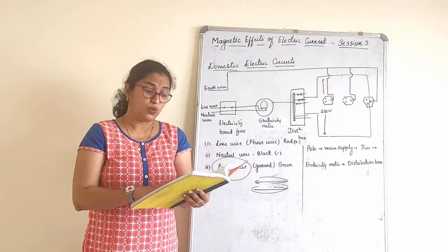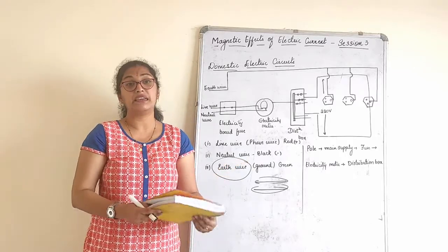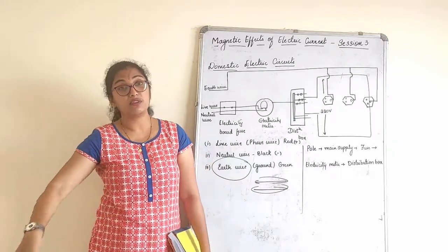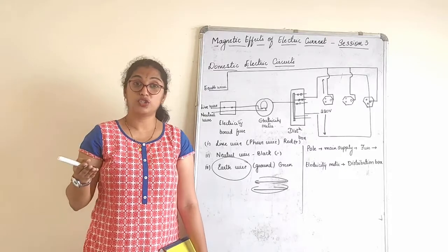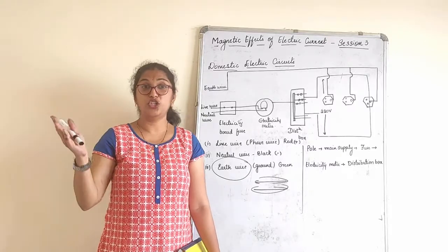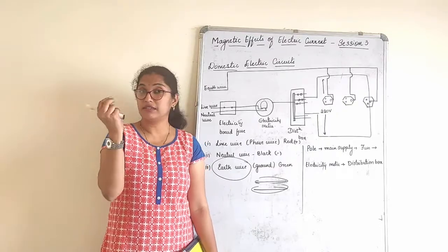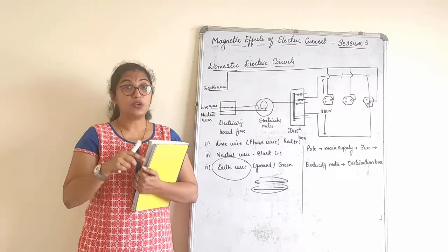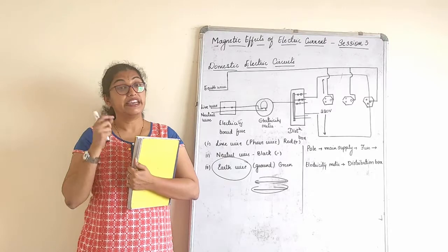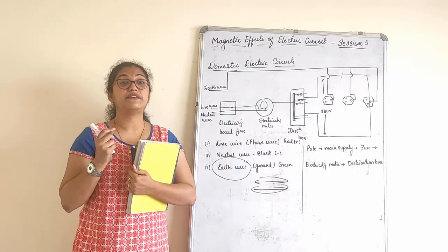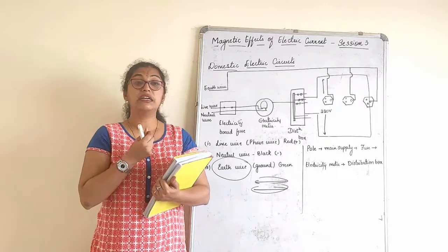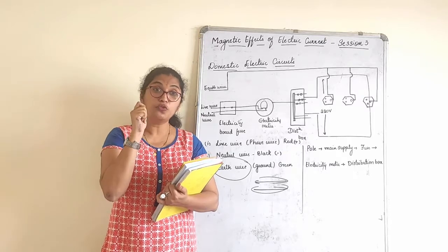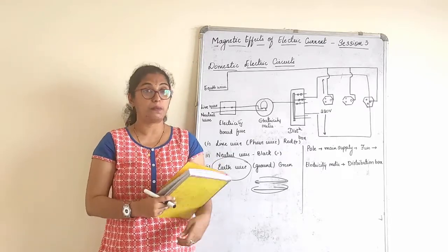What is an earth wire? Why is it necessary to earth the metallic appliances? It is necessary because otherwise the current will flow through our body and then go to earth, where we get an electric shock. Now if you have proper earthing, if you touch a refrigerator, there will be no electric shock from the refrigerator. You might have experienced this, right? That is only because there is no proper earthing at home. If earthing is proper, none of the devices gives an electric shock, neither your refrigerator nor your PC. Sometimes when you touch the CPU or try to plug in a pen drive, you feel an electric shock. It's only because of improper earthing.